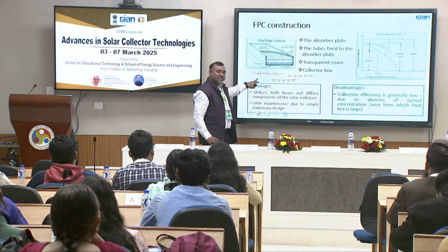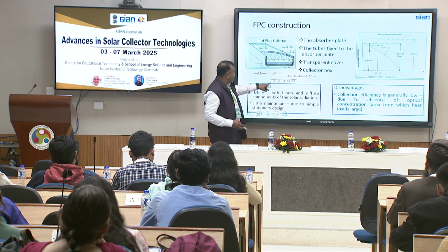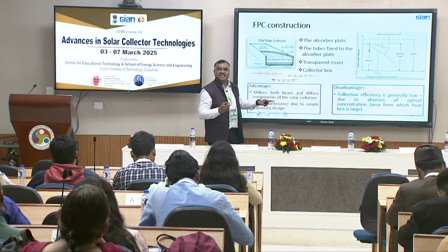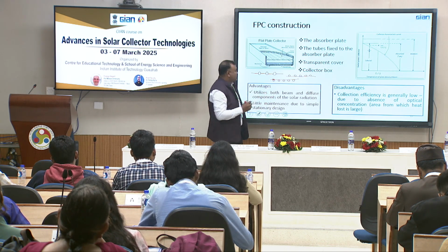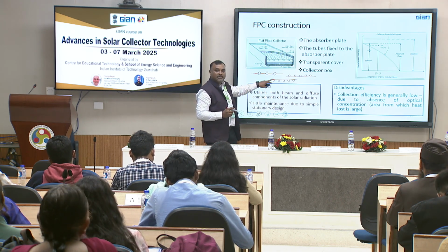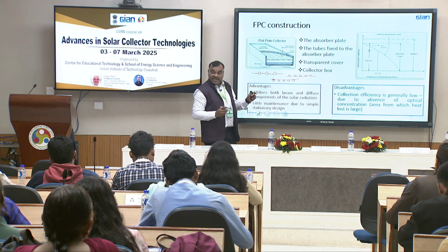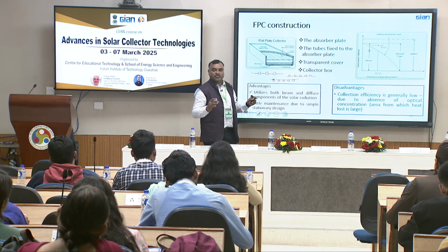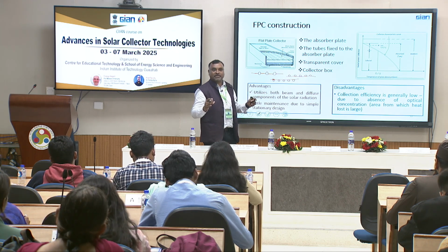While doing so, actually you can increase the efficiency, because as I said before, this contact resistance. So, something you have to apply here. This is normally pressure bonded. You have some kind of foreign materials to be there, and this actually acts as thermal resistance to the heat flows, right. So, can we remove this? So, this is the configurations by which we can remove it. Okay. Even though these are very tiny, but its impact is very, very high if you talk about thousands and lakhs of square meter areas of flat plate collectors.